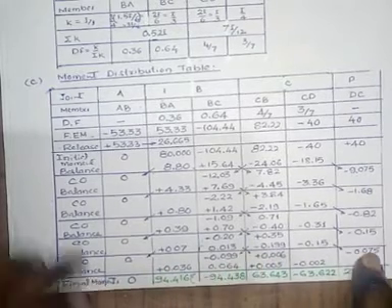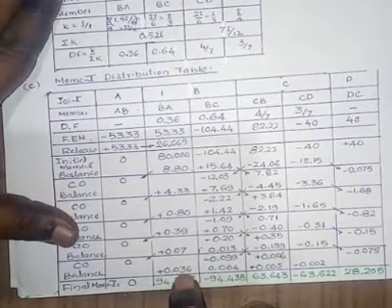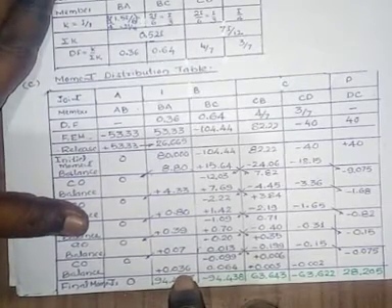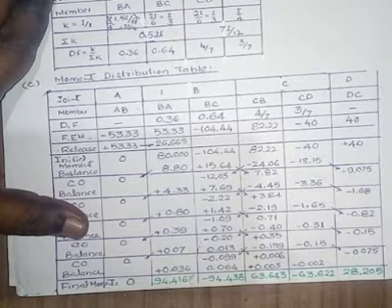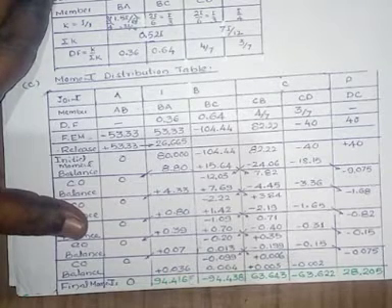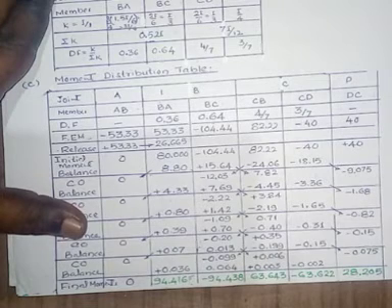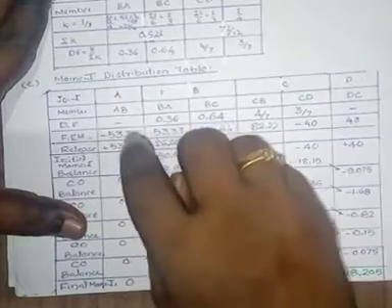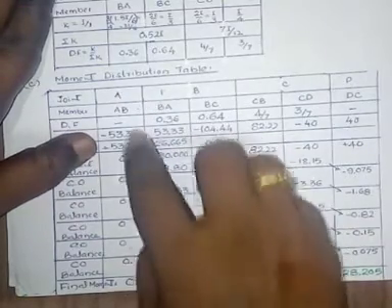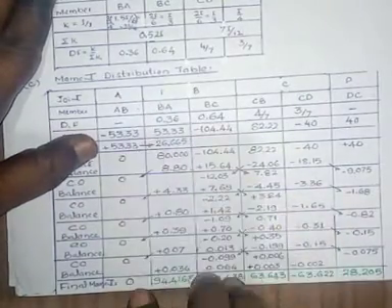Again, balance this. Finally, here the fraction is very small, that is the value of the moment is very nearly 0.01. In that condition we have to close the cycle. Then I have to add here 53.33, one is negative, one is positive, the summation is 0.